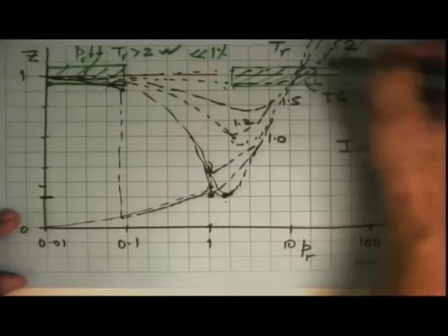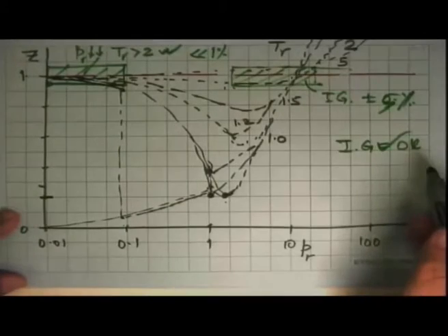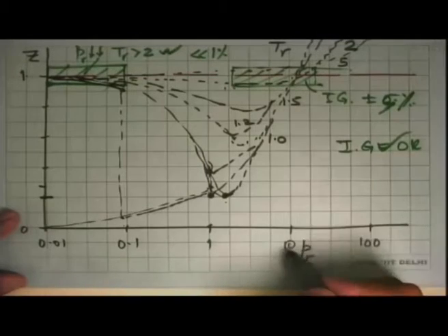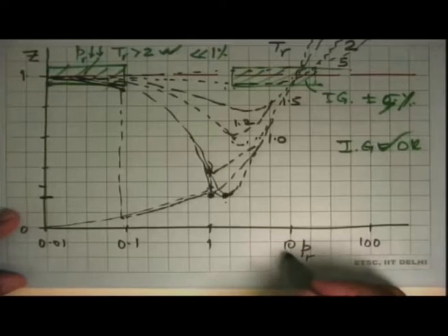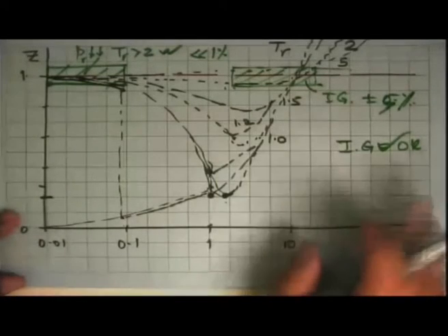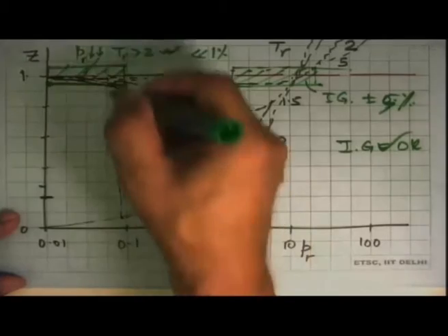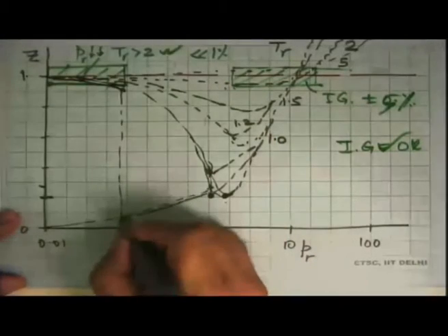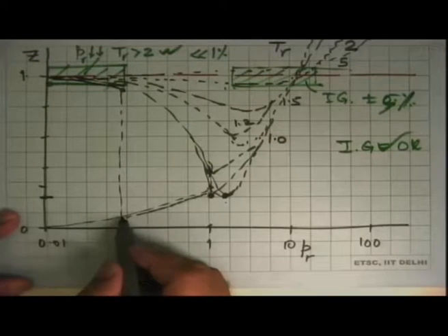And at higher pressures, no, because these curves are very steep, they go up. So we cannot assume anything beyond reduced pressure of 10 to be an ideal gas. And then again, even if we say that reduced temperature is 2, even if it were a saturated state, then also it is not okay.